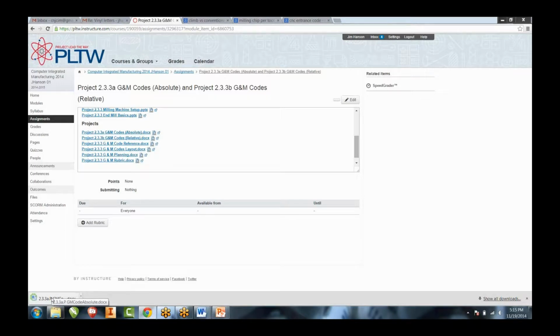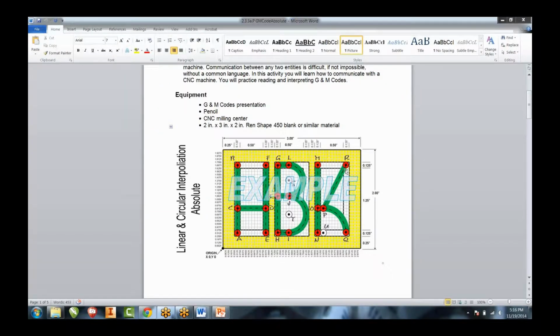What you see right there is what I have my students do. I give them little circle templates, and they draw little circles where each one of their points are going to stop. I have them draw the tool path with some dotted lines. I have them draw the outside of the tool paths with a little bit of offsets. I want them to look as realistic on the paper as they're going to be in real life, because kids have a hard time understanding that every time the bit stops, it's leaving round things in different places, and they don't pre-plan for some of that.